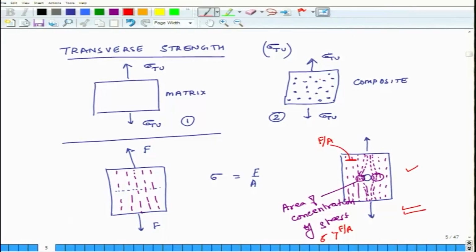Now, in case of composites, there are several such inclusions in the system. So, in general, the overall stress around these inclusions, which are nothing but fibers, right? Fibers are going in the direction perpendicular to the plane of this board. So stresses around these fibers are significantly higher compared to sigma, this external uniform stress which we are applying.